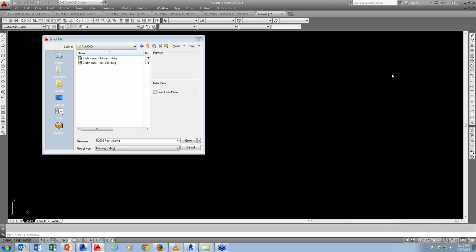For fading backgrounds, let's say for example you have a 3D solid or 3D model and you want to get that depth of field. In Revit, you can actually do it. I'll show you a simple tool, very easy. Whereas in AutoCAD, you can still do it, but it's very tricky because you have to go through the viewport. You cannot rely on the model space. And finally, 3D snap. Sometimes you want to query a point, let's say what's the elevation of this 3D point. You can do it with AutoCAD, whereas in Revit, it's very difficult. I'll show you later on what I mean by snapping.